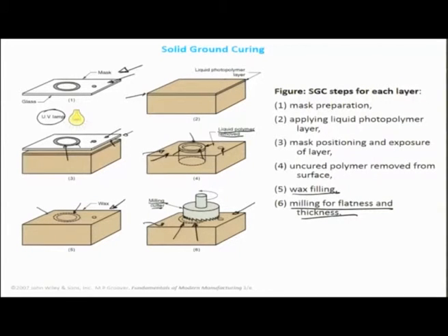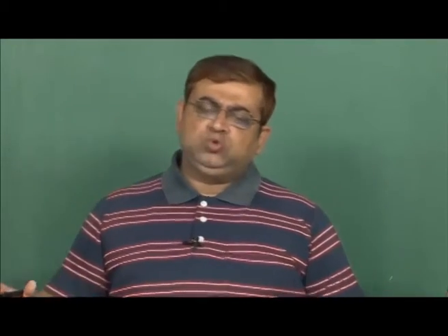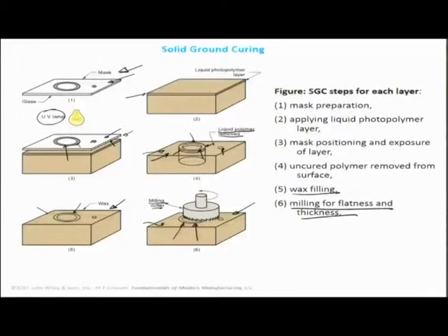through mostly an aerodynamic wiper. In this case the liquid polymer is such that whenever it's not cross-bonded to the substrate or to itself, then it is flowable enough and the viscosity is low enough for the liquid to drain off the surface. So you are draining the liquid off the surface again, thus keeping a small solid portion on the top. Okay, again do the wax coating, again do the micromilling, and in this manner you build this particular cylinder, hollow cylinder, layer by layer.